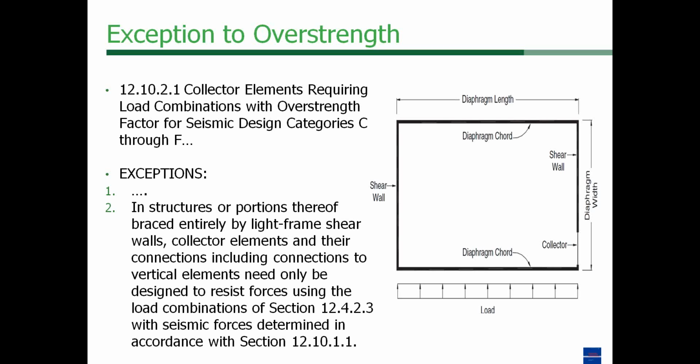Bolts and lag screws in particular have very high safety factors, and while the safety factor for nails may not be quite as high as what you might see for bolts and lag screws, the nails tend to be very ductile. So we don't see brittle failures in collectors, rather we see a stretching of the element as it overloads.